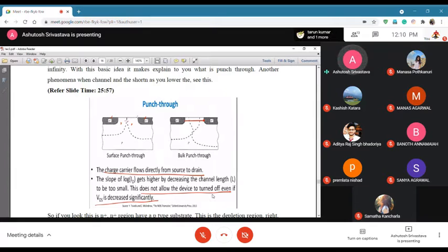That is why when we say technology node, you will hear all throughout your life 1 micron, that is channel length, or 10 micron when it all started way back in the 1970s. Sometimes it's also called gate length, sometimes it is defined by different companies in a slightly different form. But it all is talking about the same thing, which is channel length or gate length.